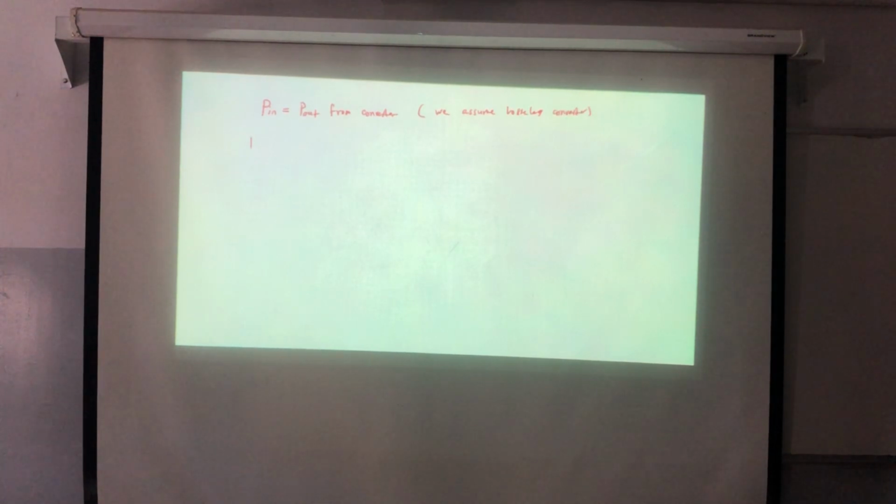So the P out from the converter will equal V terminal or VA times IA, correct? VA was 463, multiplied by IA, which is 130, it's given. If we do the math, we can calculate this to be 60,191 watts.